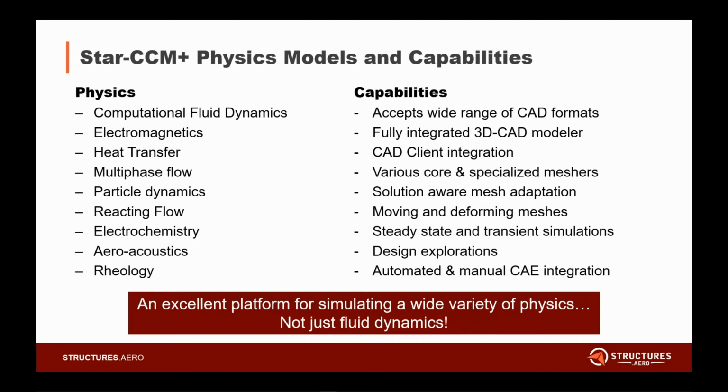STAR-CCM can also tolerate moving and deforming meshes. You can specify, like, a rotating tire or propeller in a steady state simulation, and then you can also, of course, do steady state and transient simulations, so time dependent and not time dependent. There's also software capability for design explorations where you can set design variables and then have STAR-CCM run through the whole design space and tell you, hey, this is the best direction to go in.